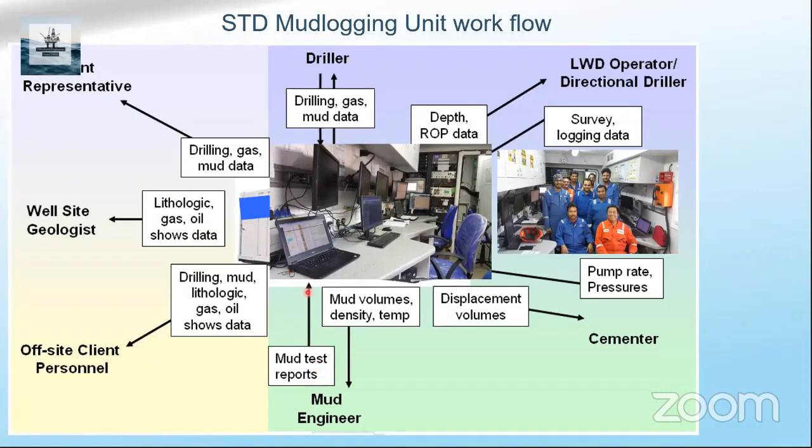The mud report, he will check from time to time, what is the mud weight or density going on, and what are the mud properties, and any addition of new mud, any transfer or any addition. The mud engineers and the mud loggers need to have very close communication, otherwise there can be a false alarm. If the mud engineer is adding mud and the logger is not informed, they will think there is some influx from the formation. And then the LWD and MWD, as I mentioned, in this case it was together, so not an issue.